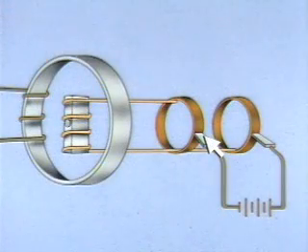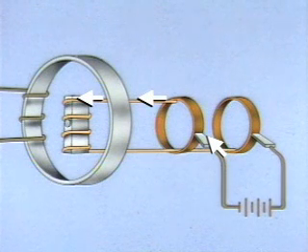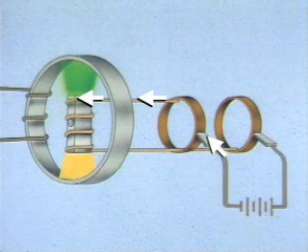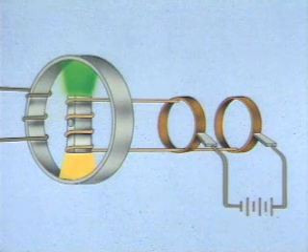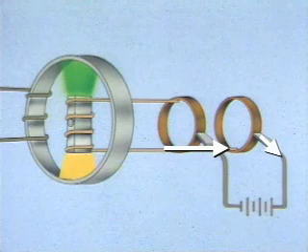Current flows from the negative side of the DC power source through one brush to a slip ring. From there, the current flows to the winding around the rotor core where it creates a magnetic field. To complete the path, the current flows from the winding to the other slip ring, then to the brush, and back to the positive side of the DC power source.